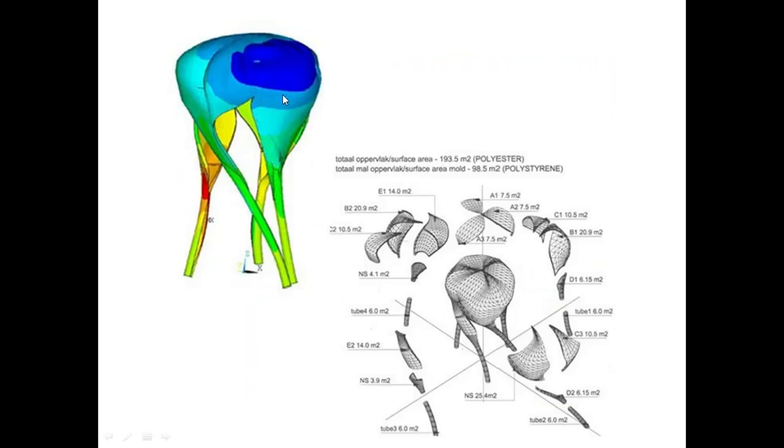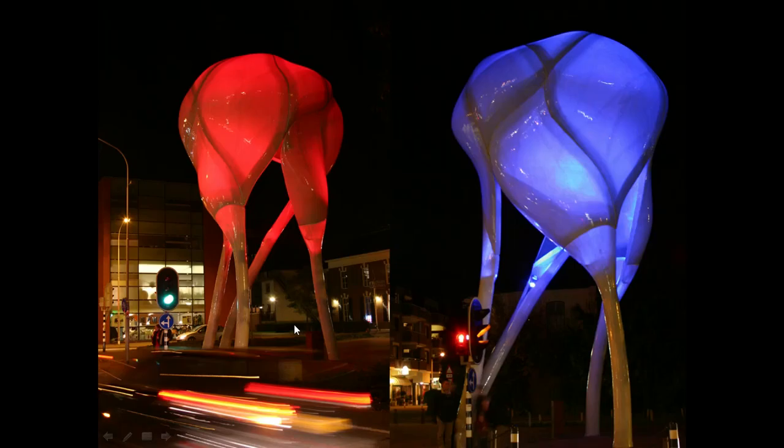And here's the finite element analysis of the structure, which is sort of Gothic. It's a vault again. It's basically a Gothic kind of structure, isn't it? And here's all the parts. Here's all the sections that were then bonded together as fibre reinforced plastic. What else could you have built it from? Because it still has that lovely translucency, doesn't it? Which is rather nice. Which is why it would have been fiberglass and not Kevlar or carbon fibre, which probably would have made it a lot less translucent.